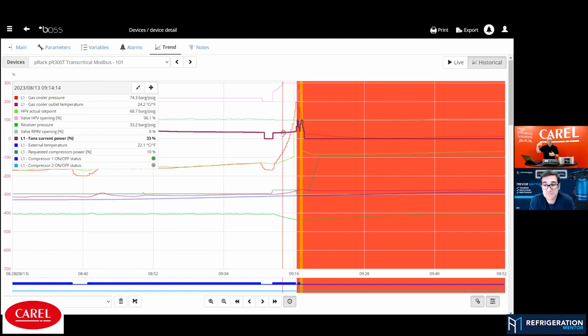And they don't need to run at a higher level. So we don't have a high temperature issue or something like this in our gas cooler. Maybe sometimes a gas cooler is standing outside, and you have some paper flying around, or some plastics flying around and get sucked by the gas cooler, and it completely closes the gas cooler. So then you also run into high pressure problems. But we would see it. Our fans would go higher, and we would see also the difference in the outlet temperature.